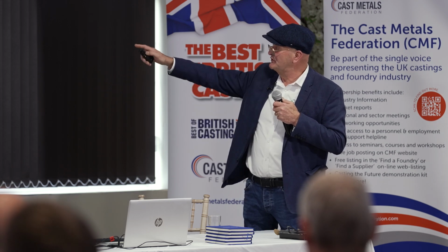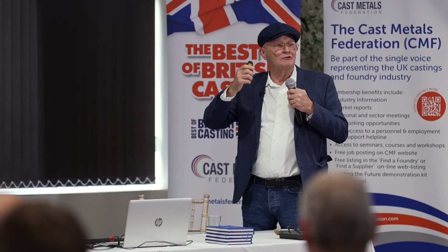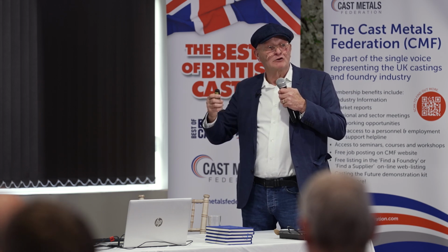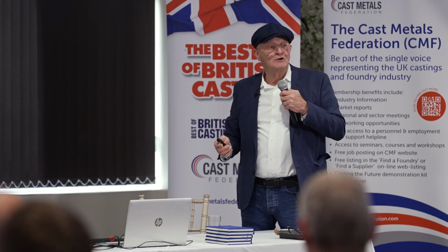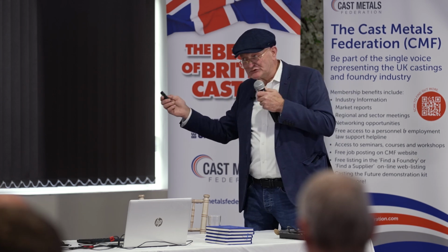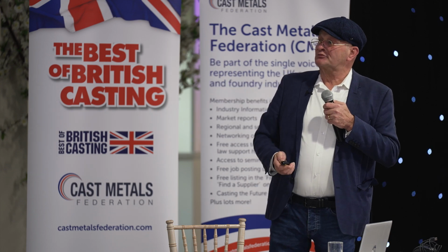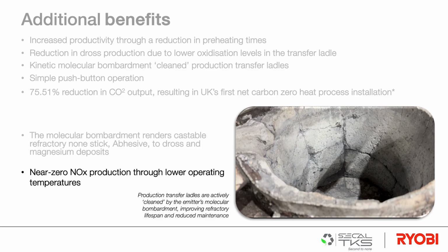And it enables them to effect very good repairs to it. You're not shocking the refractory. You will actually get a longer life, which we've trialed before. We increase refractory life by about 20% as a result of using the kinetics. Near zero NOx production through lower operating temperatures again.